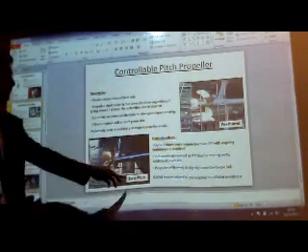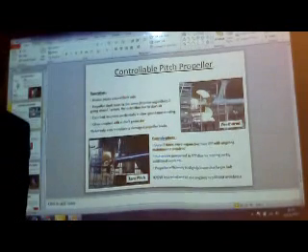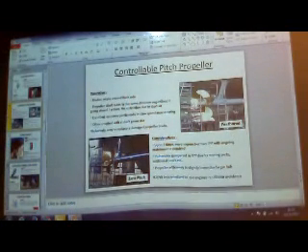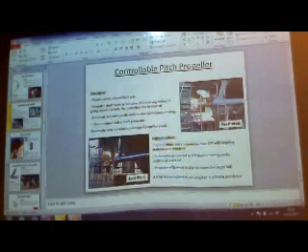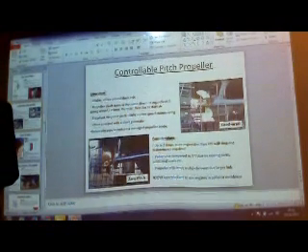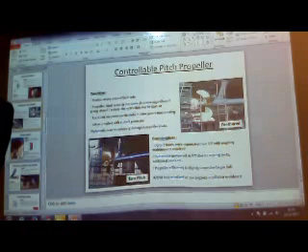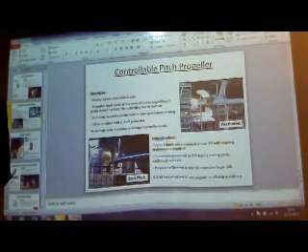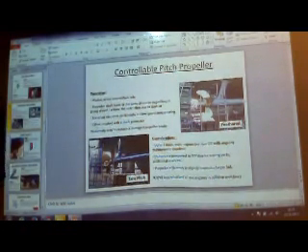Another problem is zero pitch, which a lot of people are not aware of if they have not sailed on these kinds of ships. Let's say your ship was moving with a good linear velocity, and suddenly you make your pitch zero. What will that do? It will not cause any propulsion, but that leads to another problem, because your propeller is continuously turning at an RPM.